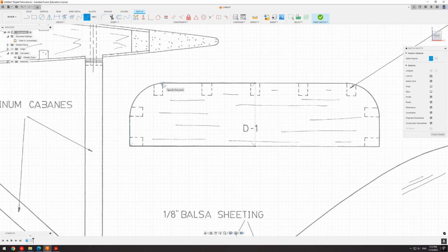Then we're going to make a few clicks, and we're just going to rough this in here. We don't need to be very accurate. Okay? So we know that the line connects to this top line here and there. So we're just going to go ahead and click. We're going to come out here. Don't make a straight line. See how Fusion wants to snap you to a straight line? Don't let it do that. You can hold control, and then that'll temporarily turn off the snapping, as I'm doing here. Or you can just make sure that you're not on that straight line by dragging down a little bit before clicking. Now click a few times, and then come down and connect to this vertical line here. Then hit OK.